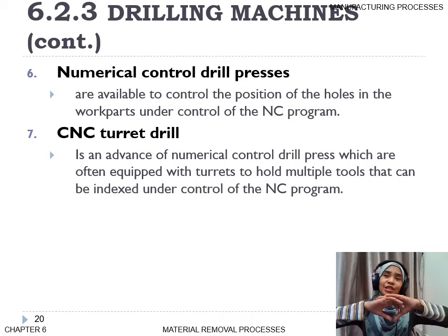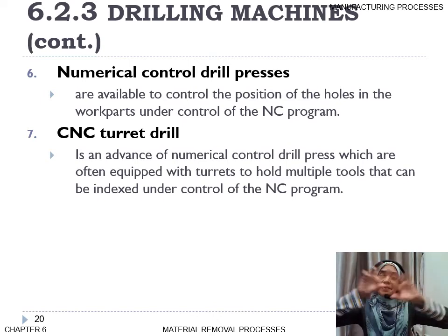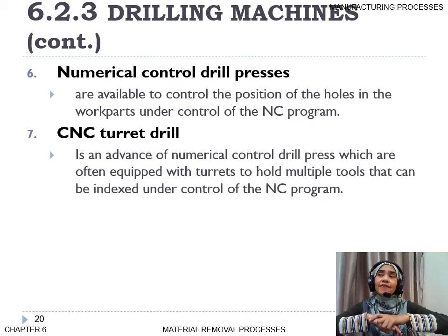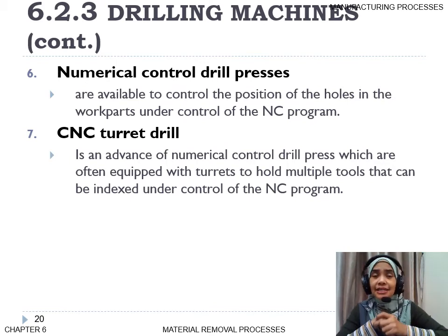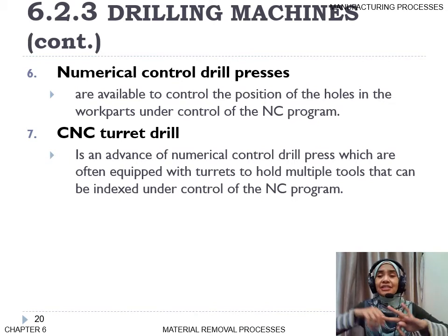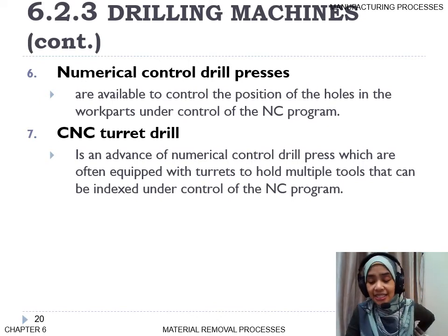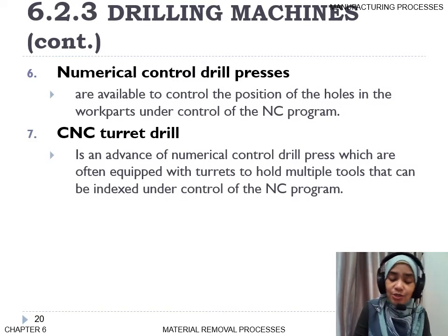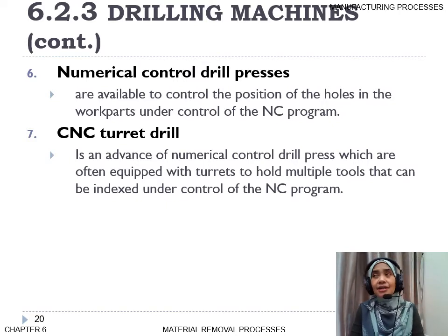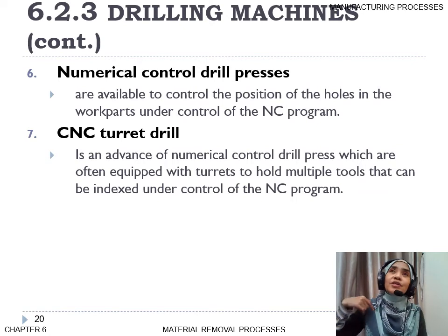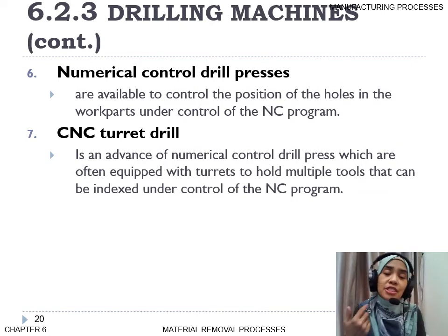So at the tool post there is a tool changer. We have already installed the kinds of drill bits needed, for example centering, then drill, reamer, and then tapping. You just set in the program which comes first until last. So the machine will change the tool in order, as instructed.